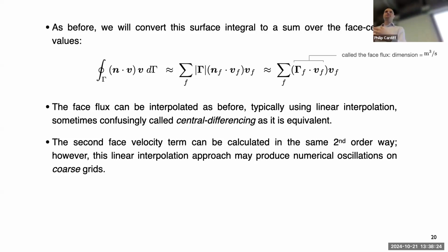The same thing happens in all numerical methods. You get zero energy modes in the finite volume method. If you use central differencing here, you will sometimes get checkerboarding style error, so you might get the pressures and velocities peaking cell to cell. So they normally will try to interpolate one of these velocities using a slightly different method to stabilize it in some way.